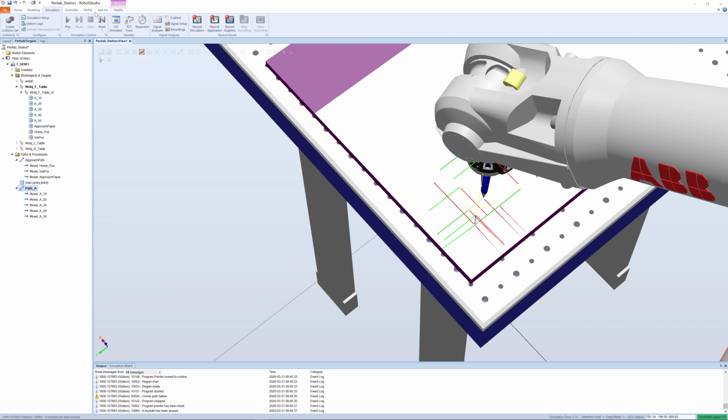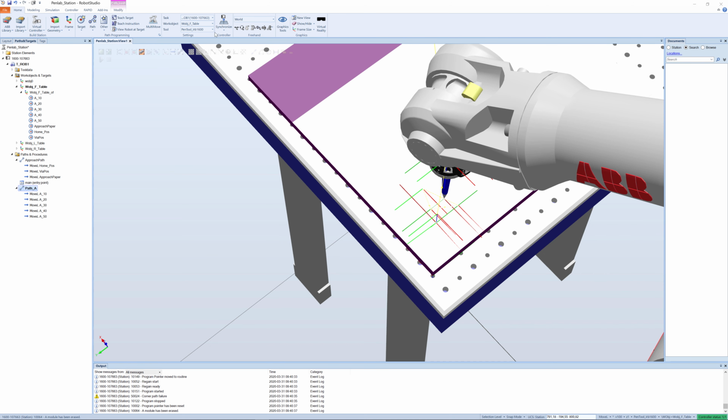Okay, so we go to the Home tab and make a synchronization to the Rapid. That will actually generate code, but before that we make sure that we have something in the main entry point procedure. We can do that manually in the editor, so that's not a problem in itself.